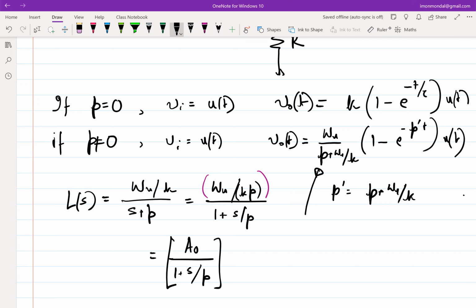Yeah, you would like to know where the omega naught falls, right? Is it below, before, or after? So now let's assume it falls below, it's within the loop gain. So let's assume omega naught is less than omega u loop. So then what will be my output? K times Vp sine.